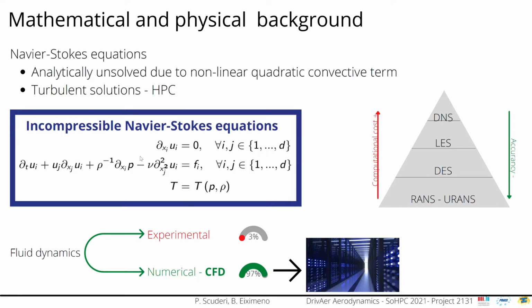In our project, the fluid regime is incompressible and turbulent. The turbulence is directly predicted by the Navier-Stokes equations. It is associated with the presence of three-dimensional vorticity and dissipation at the Kolmogorov microscales. Turbulence treatment does not provide a unique solution.